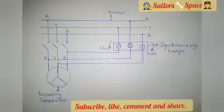So if it is going in the clockwise direction, that shows it is fast. That means your incoming generator is fast. Either way, if your incoming generator is slow or fast, you trim the governor of your incoming generator to either increase or reduce the speed to match the frequency. But you should note that the frequency of the incoming generator has to be a bit higher than that of the running generator so that it will be able to take load.